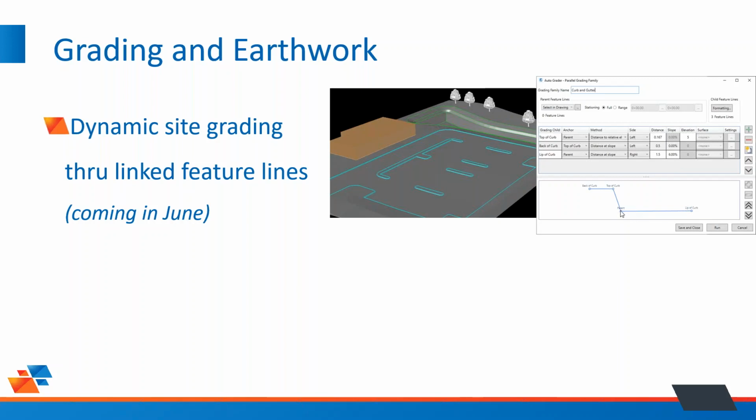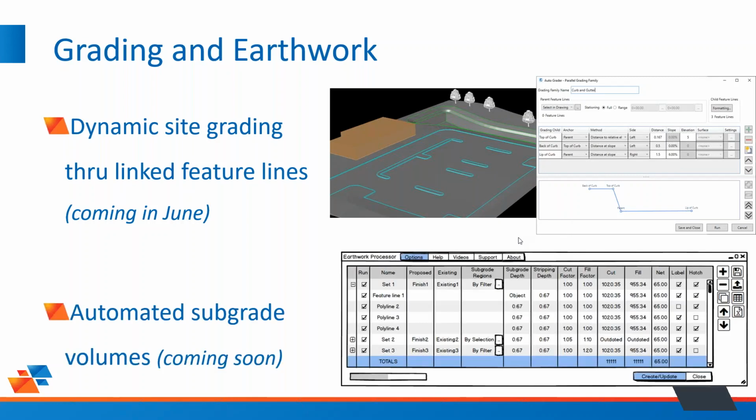If you draw a gutter line, you can then define a grading family that'll automatically create and update top of curb, back of curb, flange, you name it. Think about ponds, think about all different kinds of scenarios. I'll give you a detailed preview of that.